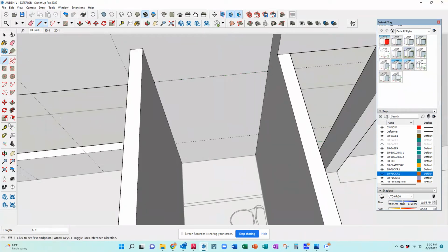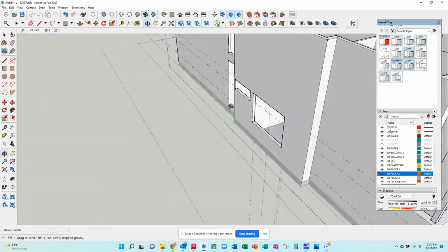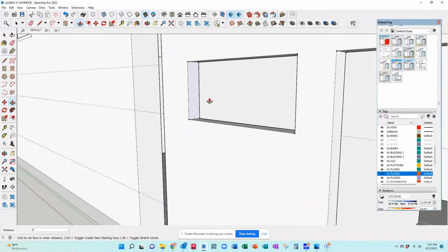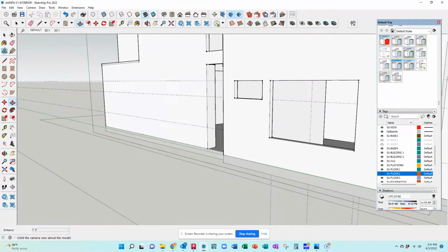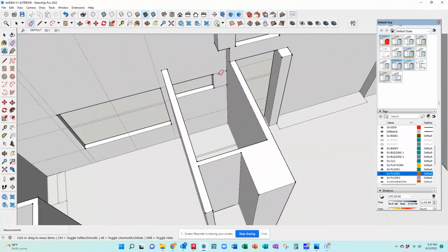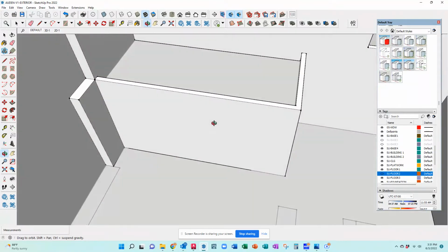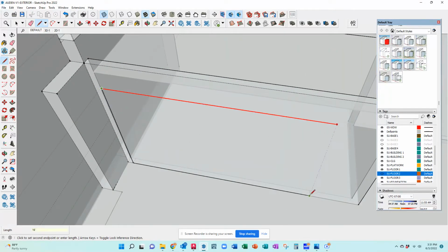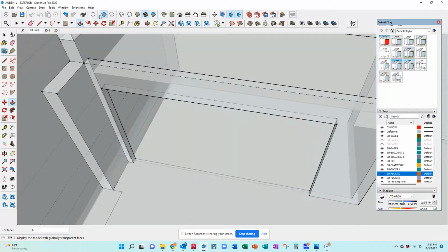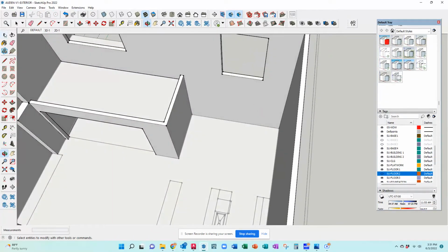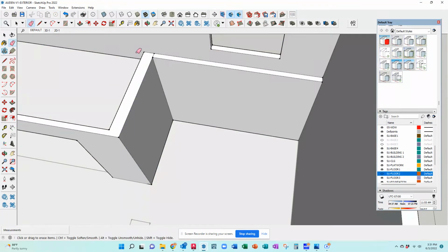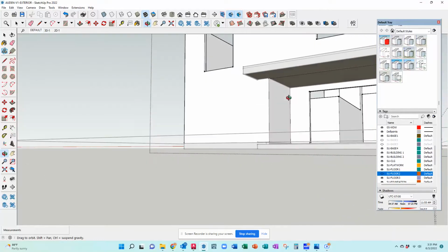For the windows I'm punching in now, if we're not quite sure of a window location or size, I'll just do an outline at this point. If I'm pretty confident of where I want it to go, I'll go ahead and punch the hole through the wall. That's a bathroom, actually, a high window in the shower. I was going to do it wall to wall, but when we look at it on the exterior, the proportions just looked wrong with that thin edge, so I shrunk the window. That's the great things we can play around with and see in SketchUp and easily modify.